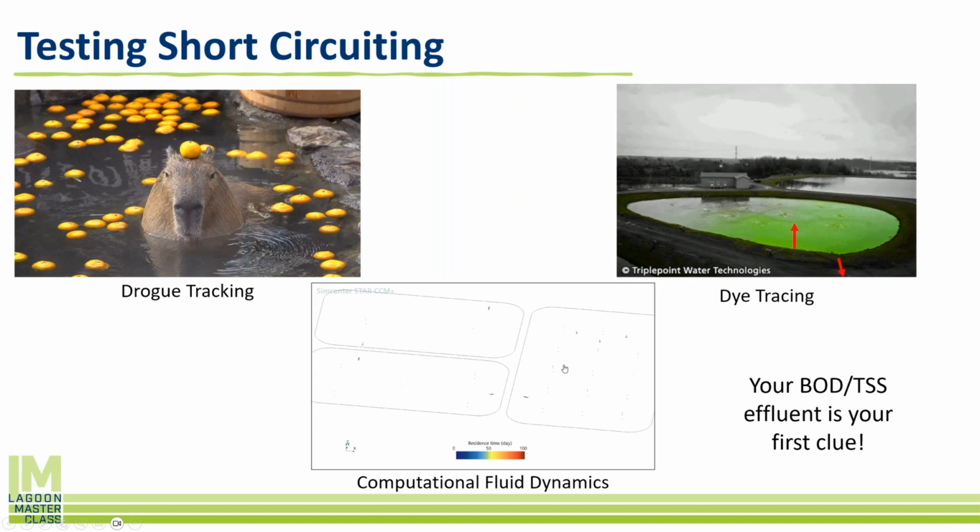I think one of the simplest and quickest ways, without spending a couple thousand dollars on rhodamine dye tracing, is using what we call a drogue. You might know drogues from sailing or from fishing, but the idea is putting something in the water that sits low in the water and moves with the water, and that we can track. You can buy expensive geologic survey materials, drones that are crazy. I don't recommend you do that. They can be very, very expensive. You can use something as simple as an orange.